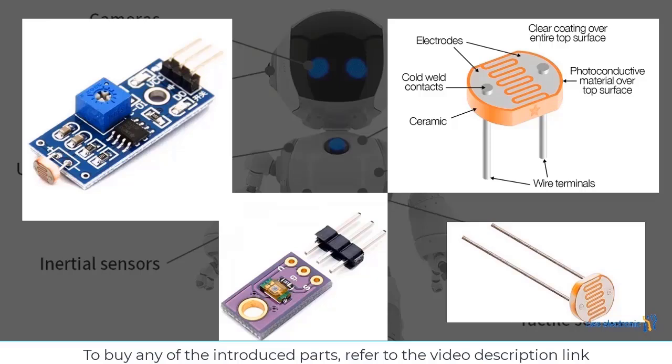There is another type of light sensor called a photodiode, which is different from a photocell. In fact, a photodiode is a diode that, when exposed to light, generates a very small voltage of a few millivolts. So it somehow generates electricity in a small amount, which is enough for a sensor to sense. Because by increasing or decreasing the intensity of the ambient light, this voltage produced also increases and decreases. And based on this, we can calculate the amount of ambient light. The main difference between a photodiode and a photocell is exactly here, that the photocell never creates a low voltage with light radiation.